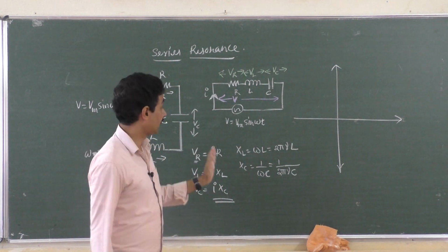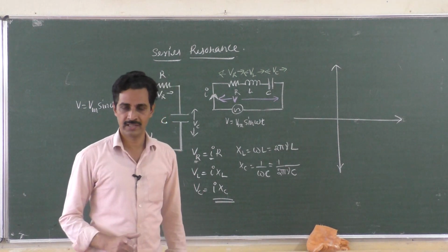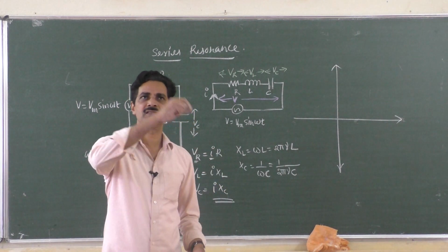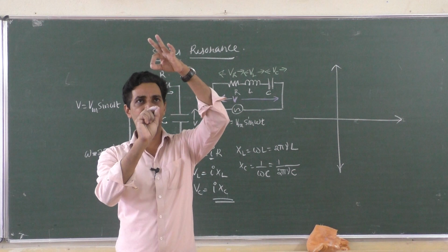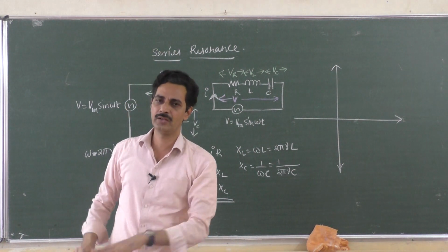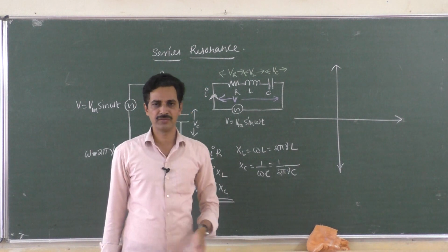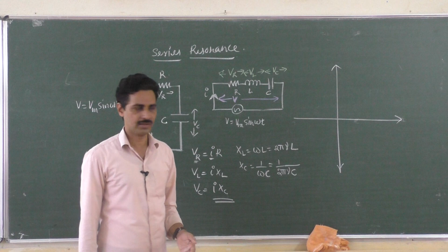And you know that when that current flows through the resistor, it produces a similar voltage which is in phase. Because in a resistor, when current reaches its highest value, the voltage produced will also be the highest. They reach highest values, zero values, negative values together. They are in phase. A resistor doesn't provide any phase difference for current and voltage. Both will be simultaneously maximum, simultaneously zero.